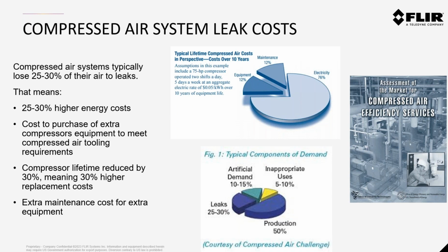And really those costs are identified here, where the demands of the equipment are, if we look at the breakout, only 50% is really tied to actual production activities. Artificial demand, leaks, and inappropriate uses make up the other half, but that leak percentage is rather large. And those are things that we typically can focus in on with these acoustic imaging devices. We'll identify the source of those leaks as well as quantify them to determine how much it's costing you every year for those leaks in particular.